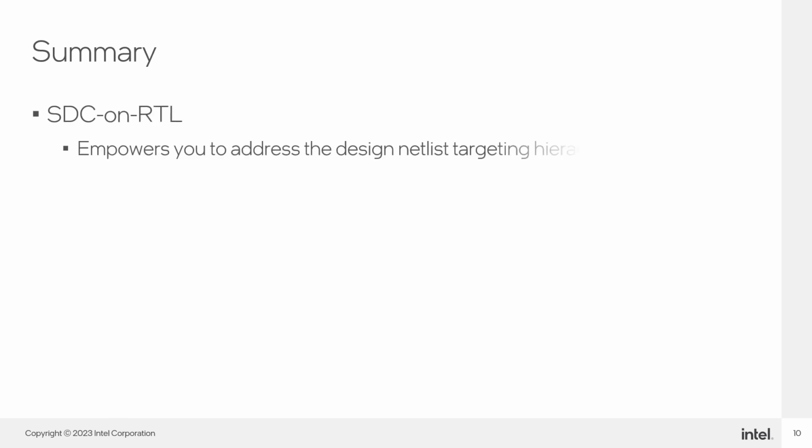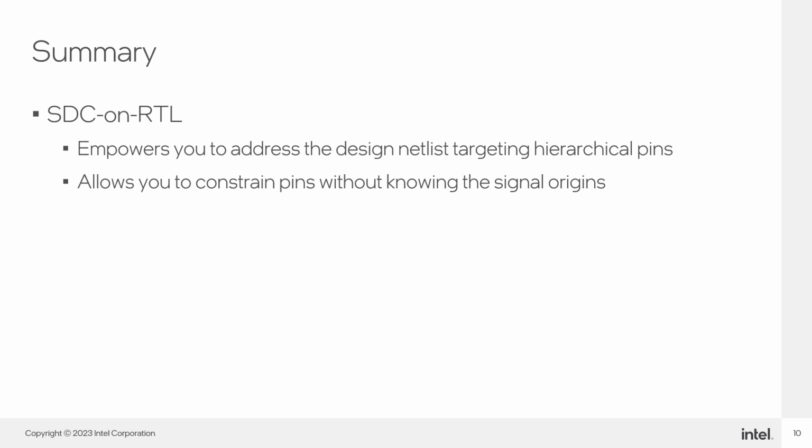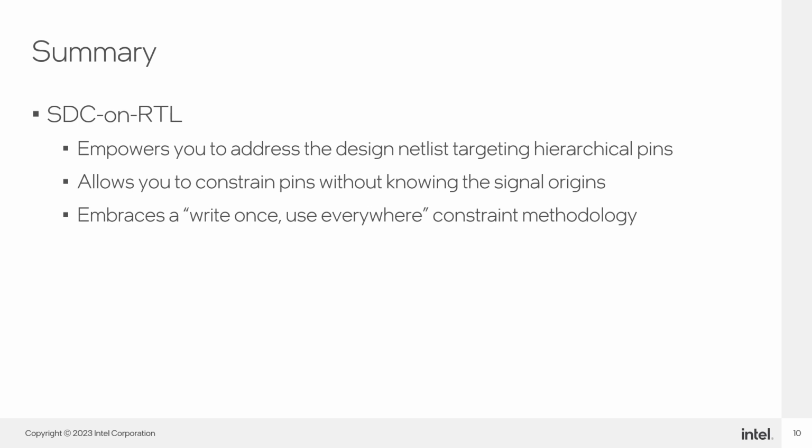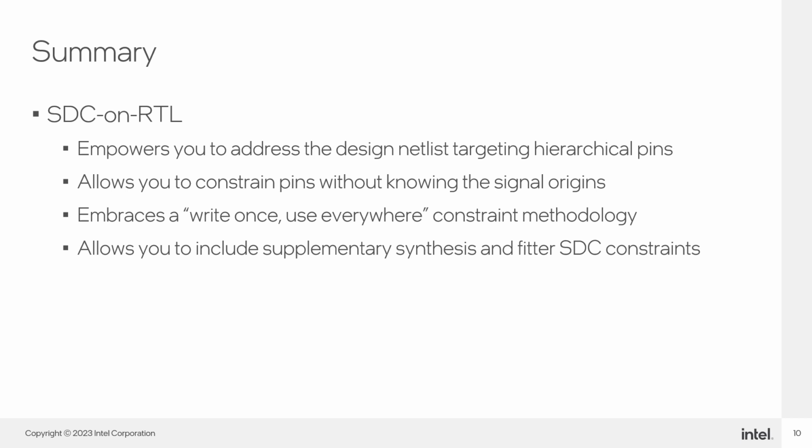In conclusion, SDC-on-RTL empowers you to address the design netlist comprehensively by targeting hierarchical pins and module boundaries, even without the need for in-depth knowledge of node names or signal origins. It embraces a write-once-use-everywhere constraint methodology while offering the flexibility to include supplementary synthesis or feeder SDC constraint files, making it suitable for various design scenarios.